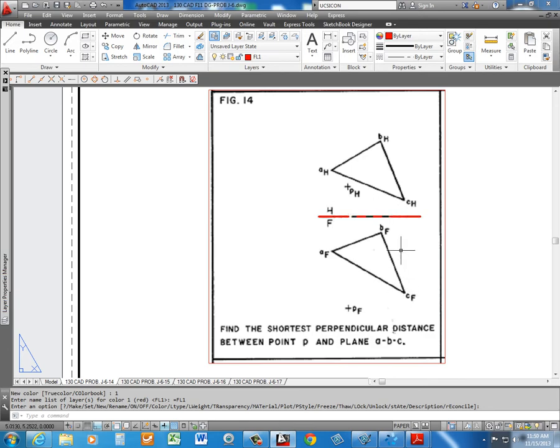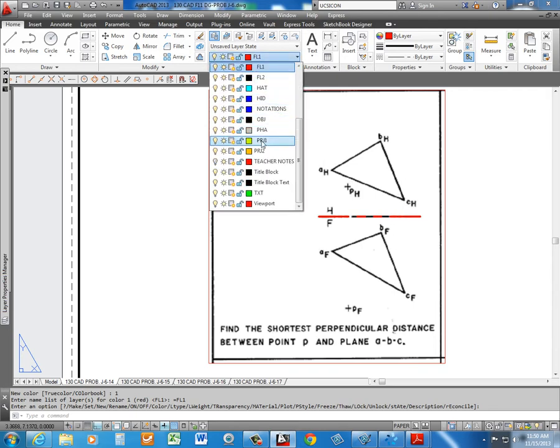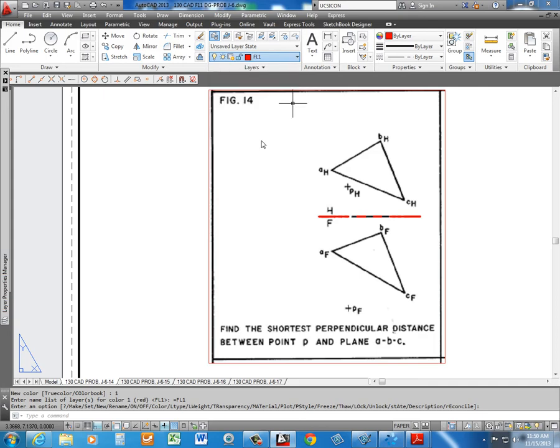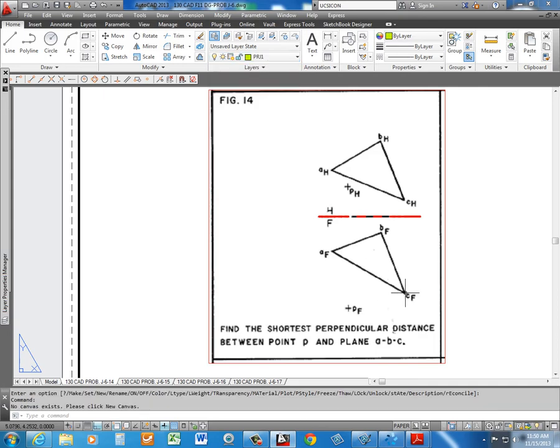Now we project between the views. We'll have to make a little correction since this is a graphic that we're tracing, and it has obviously come in just a little skewed itself. So the perpendicular lines may not match up with the points, that is the perpendicular projections. So let's go to projection 1 and we'll begin.